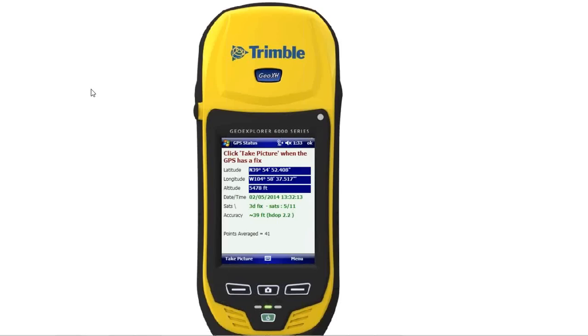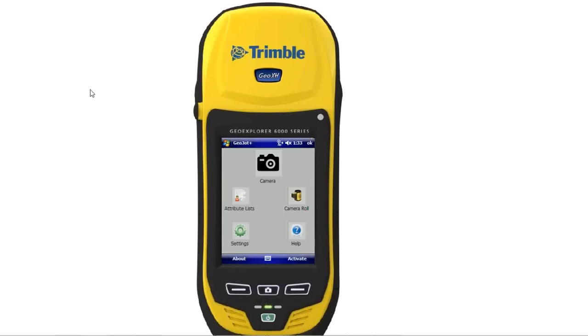All right, so somebody's asking me, John is asking, what is the accuracy of the GPS on Windows Mobile? Well, the accuracy of the GPS is going to depend on the GPS unit itself. GeoJot uses the highest real-time accuracy that the unit can provide to it in the field. So if you have a unit that's running Windows Mobile and provides sub-meter accuracy, that's what GeoJot will capture. GeoJot can also use post-processed data after the fact back in the office using a shapefile, but it generally is going to capture whatever data feed it is getting.